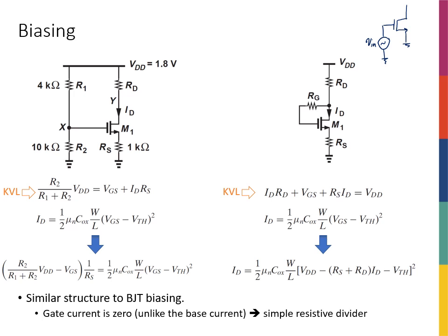Why? Because if you remember with the BJT transistors, we had this plot with an exponential relationship between the VBE and the IC. And I knew that the GM of my transistor, which pretty much sets the gain, is the slope of this curve, right?